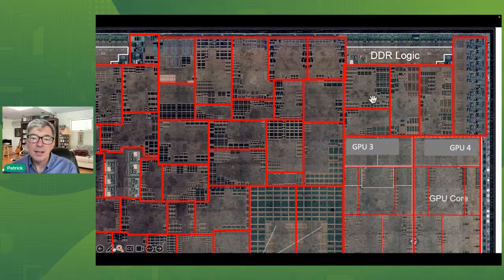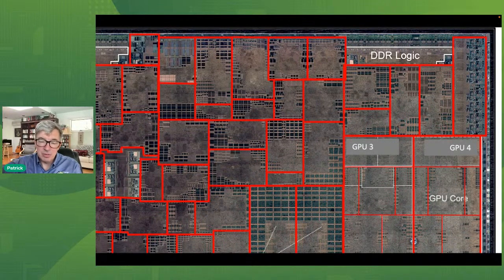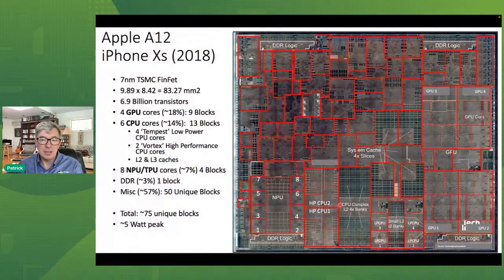Then you can see that sometimes there are two of the same blocks. The standard cells are in a big blob in the middle, whereas the macros, the memory blocks, are pushed to the side, and then we assemble them together into a large chip. So you see again the 3-level hierarchy. Standard cells, we make blocks from them, and then we place those blocks. That is the structure that we see here.